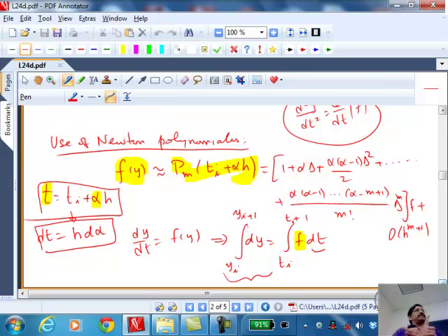And we saw the difference between the explicit and implicit: the implicit methods have the ability to look ahead any sharp changes in the solution that can occur. So they are more stable. So we introduced the concept of a stability of these algorithms, and we saw that explicit methods have a stability bound, meaning you cannot pick any arbitrary step size. The scheme will simply blow up, even though the original solution to the problem is well bounded. Whereas an implicit method will remain bounded.